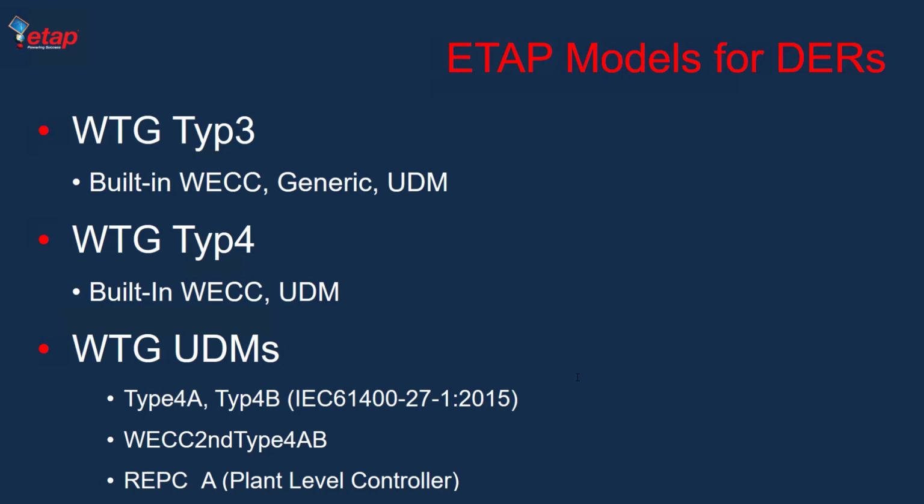These are considered our legacy models, and newer models are all based on UDM, which is user-defined models. Within UDM, WTG models type 4A, type 4B are available as per IEC 61400-27-1 published in 2015. These are more European models. Also, we offered in ETAP 20 a WECC second generation type 4A model that is based on the latest WECC models. So later on, I'll go through each one and show how they look and where you can find them.